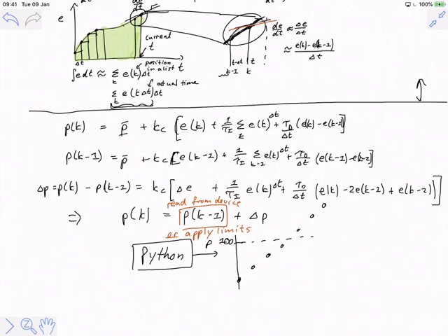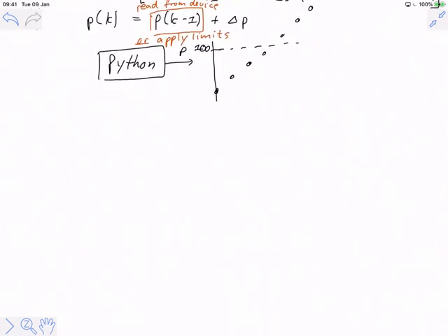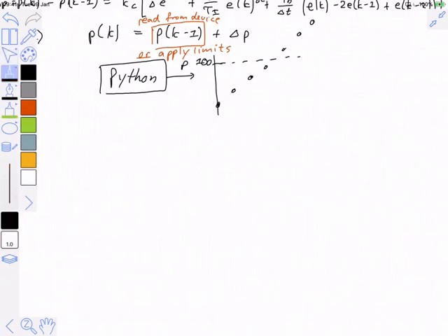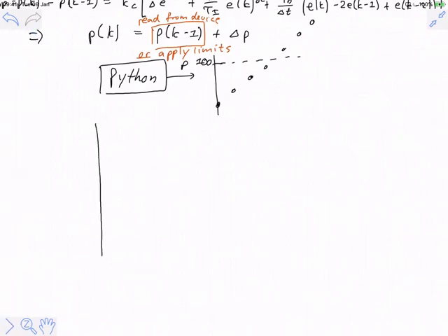The only reason why you want to make bigger changes in the real world is because you want to escape the noise bound. So when things look like this, when they're all beautifully smooth with no noise, you can start with Q at 50 and make a very, very small set point change. Make sure everything is nice and smooth.